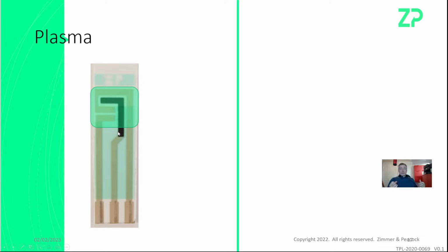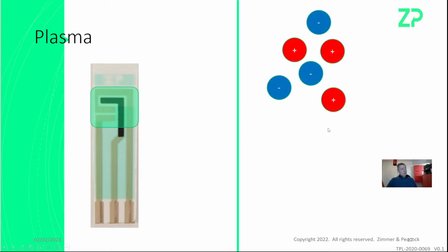But in a gas phase, we don't have a kind of continuous liquid. We essentially have gas molecules that are separated from one another. In between them, I don't want to say vacuum, but there are no molecules between them. There's not this ability for ions to have a continual electrical connection between our working electrode and reference. So if we're making a gas sensor, we often put something like a solid electrolyte on top.